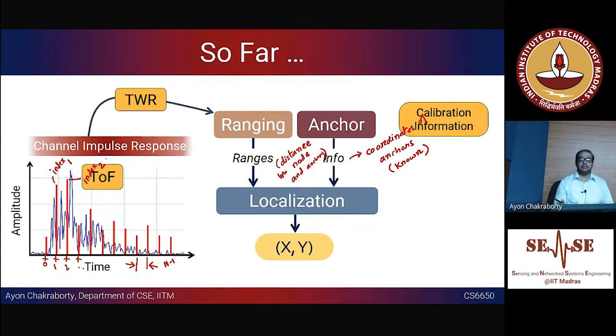Yes, of course, sometimes it might become impractical, but there could be situations where you do a one-time calibration. When you deploy the system, you also associate those anchors with certain locations. Okay, and that will be hard coded in your multilateration algorithm, right? The multilateration algorithm is going to know where your anchors are.